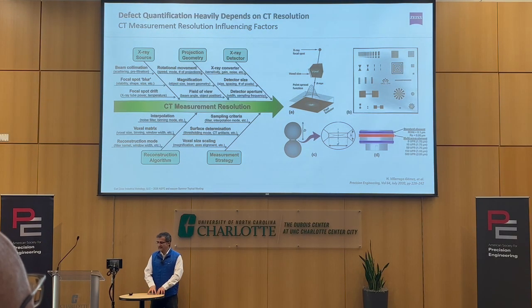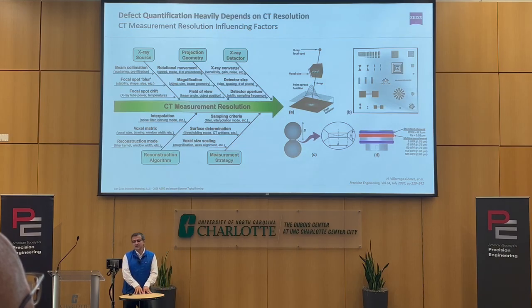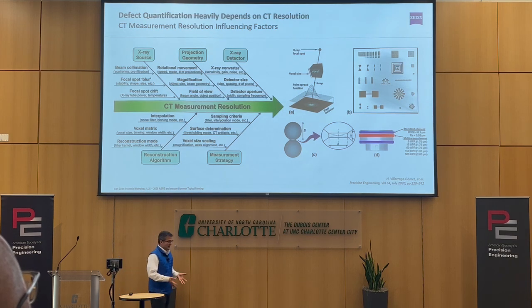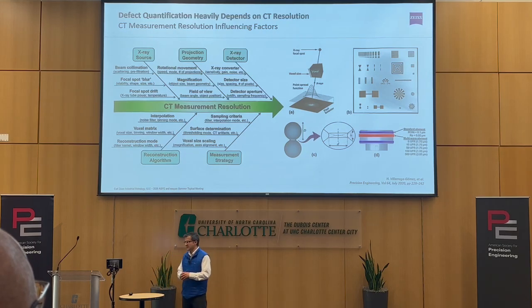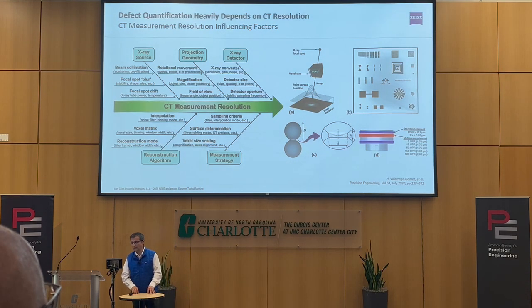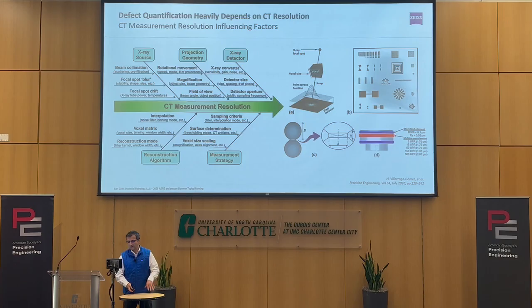But the reality is when you try to do CT measurements, you strongly depend on the resolution, the imaging resolution. And the resolution in reality depends on a bunch of parameters, which I'm not going to go into here. We also have published that in Precision Engineering with Professor Smith. And he also has designed with some of his students some artifacts to verify the resolution of a CT system, and also some of the work done at the University of Padua. But basically, the X-ray source can be an influencing factor, but also the imaging detectors.